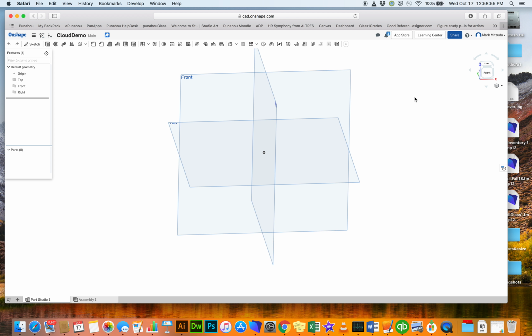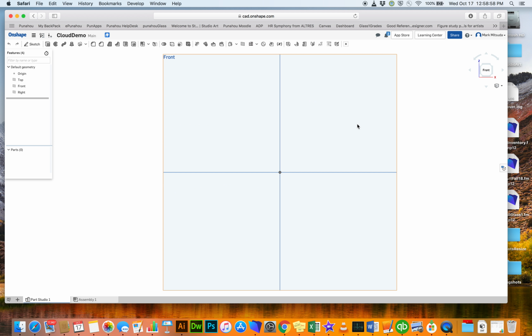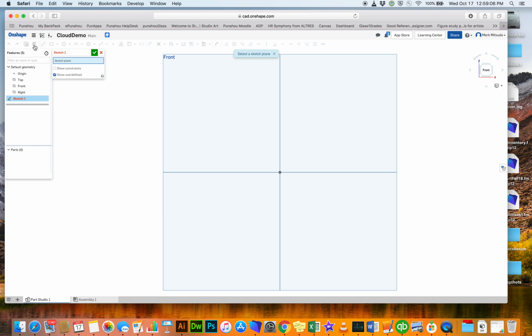Okay, I'm going to click front again. Alright, so I'm ready to do some drawing here, so I'm going to click sketch to start a drawing. It's going to open up sketch number 1, and it's going to ask me to select a sketch plane. So I'm going to click front because that's the plane that I want to sketch on.